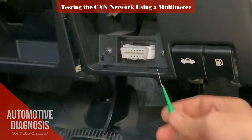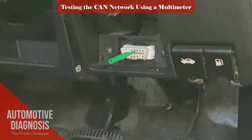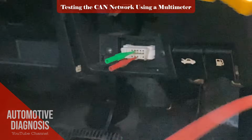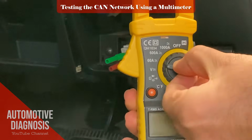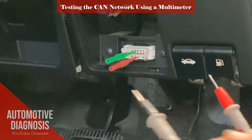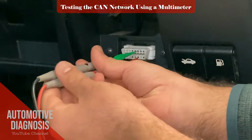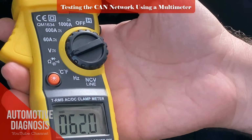Let's see how I measured the resistance in the CAN bus. Make sure the ignition switch is off, and wait until the CAN bus goes to sleep mode. Then measure the resistance between CAN high and CAN low. Your measurement must be about 60 ohm.